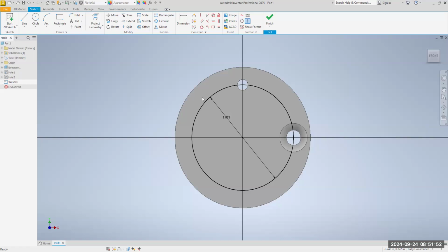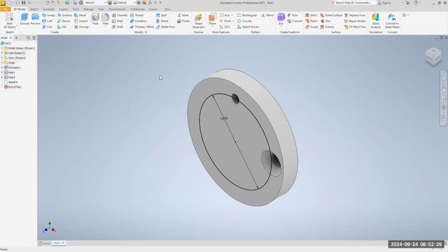All right. Mr. Morris, how do you create that? Select point, and move your cursor near the 9 o'clock position right here and click. Okay. We just located our point at the 9 o'clock position. Do a right click. Okay. It's there. I promise you the center point is there. Finish the sketch. Select hole.